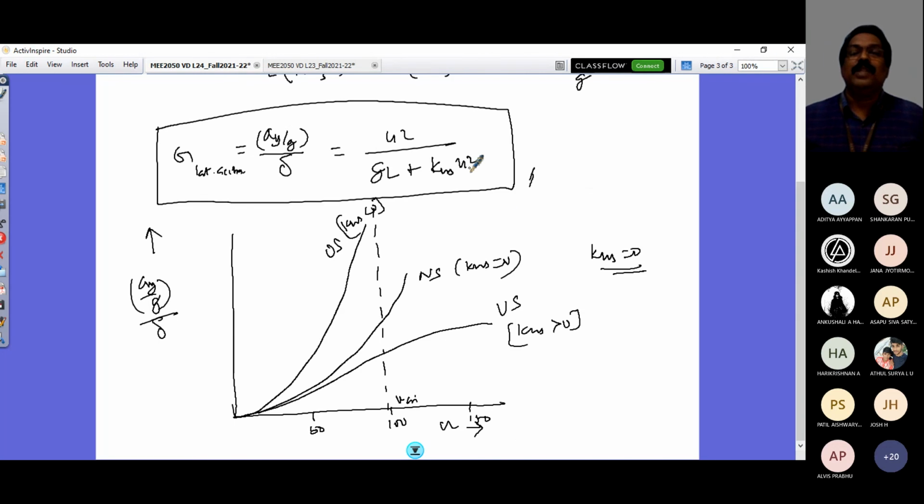So these are very simple steady state gains to readily look at and comment on the vehicle handling nature. But when you want to design your vehicle and fine tune the nature, and you have to go in for designing your control strategies, control systems, instead of looking at your steady state gains, you would look at your transfer function straight away, and those transfer functions would be part of your mathematical model. The best example is in the ride model, where you have also looked at your transfer function. So the force transmissibility or displacement transmissibility is what was there.